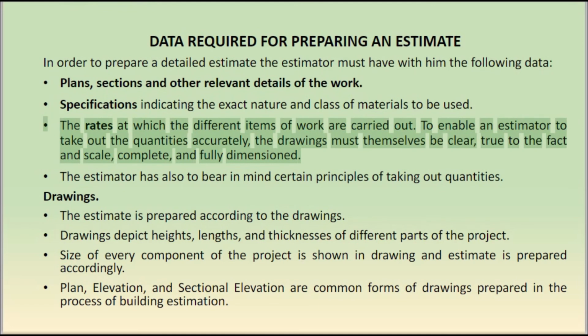To enable an estimator to take out the quantities accurately, the drawings must themselves be clear, true to the fact and scale, complete, and fully dimensioned. The estimator has also to bear in mind certain principles of taking out quantities.